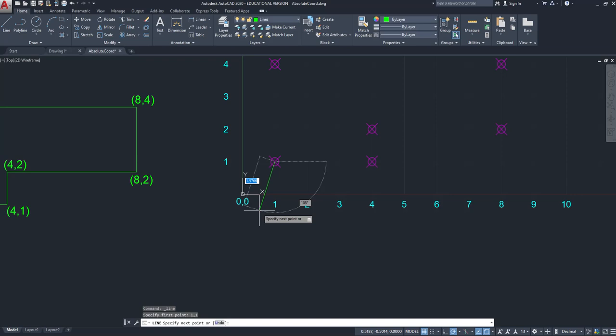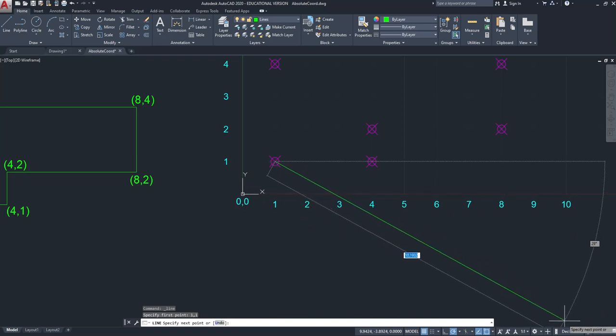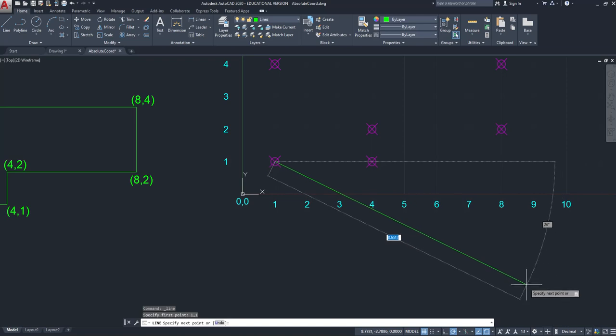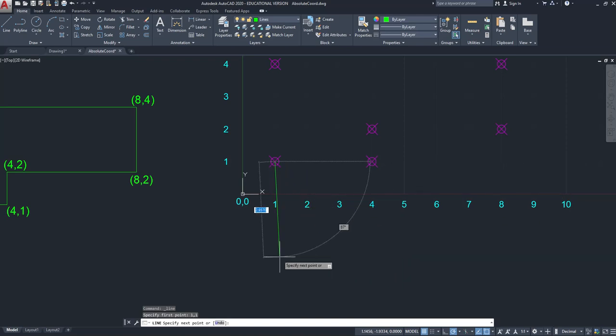So something I want to distinguish in AutoCAD, and right now I'm just going to point a couple things out. I have my units set in decimal units. We're going to leave that alone for now. But when I type 1 and I just hit enter in AutoCAD, that assumes that 1 is going to be entered in the default unit that is existing in AutoCAD here.